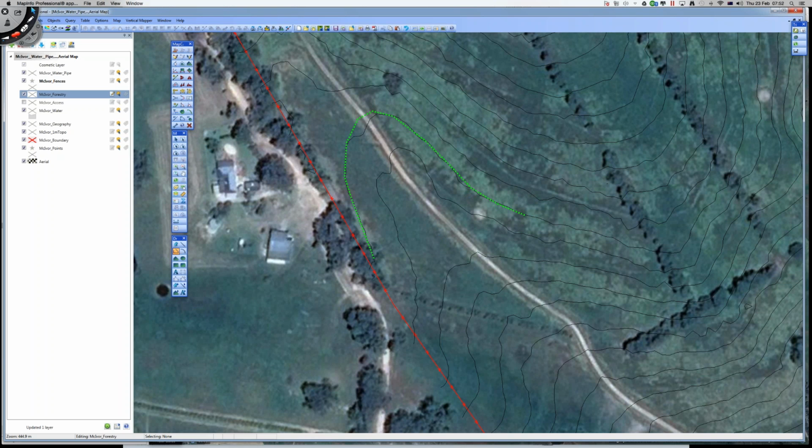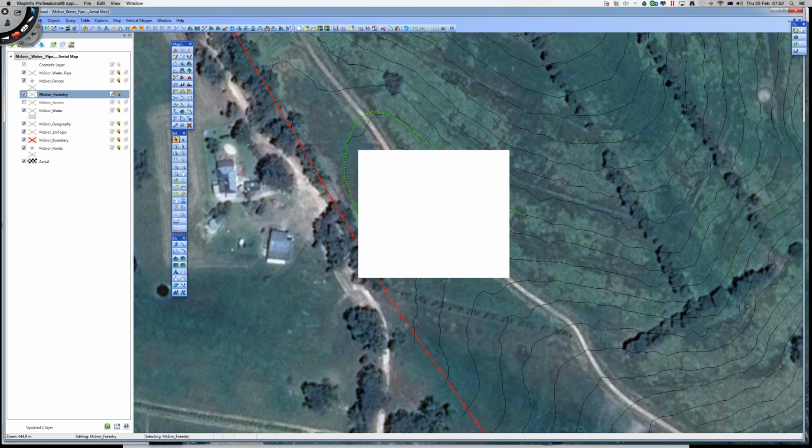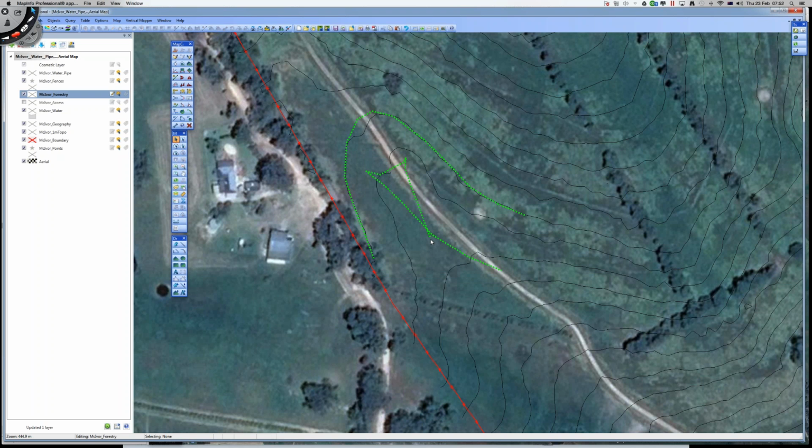So that's that line. Now I'm going to parallel offset that. I just smoothed that out because, oh goodness, when you get those sort of irregularities, just move on, just smooth over them. So I'm going to make, let's say, an alley system. So I'll go 40 meter spacings, keeping in with what we're doing. And I've gone to the right, so that should go inside. And it does.